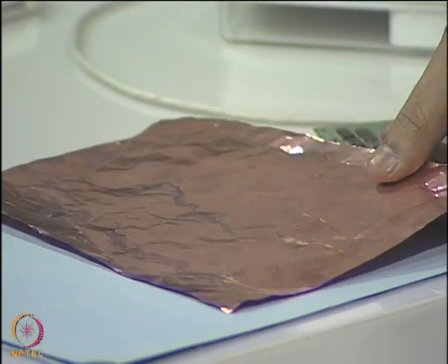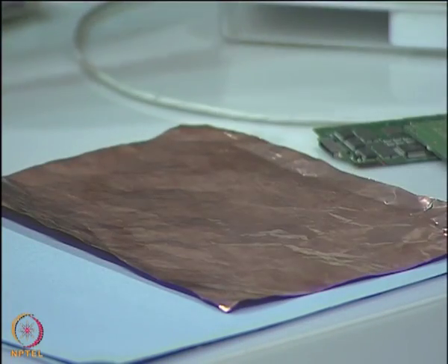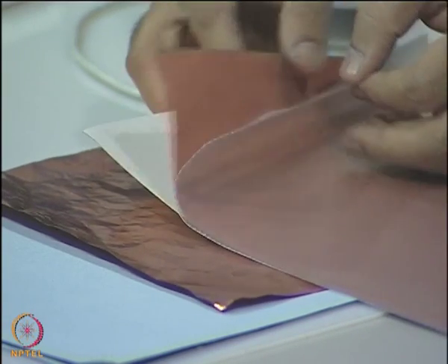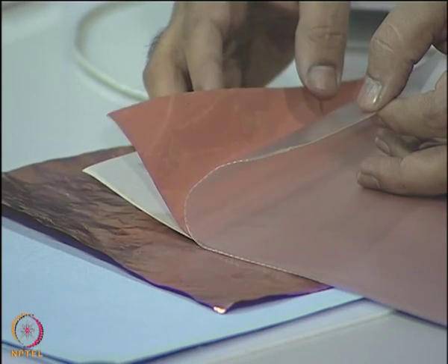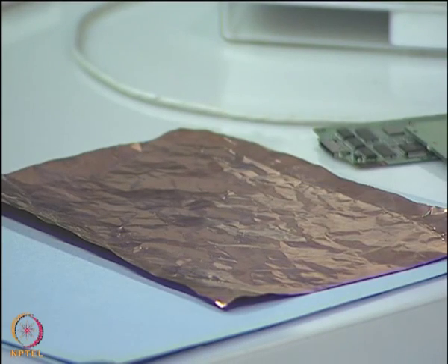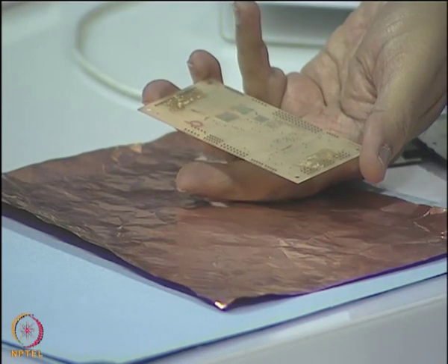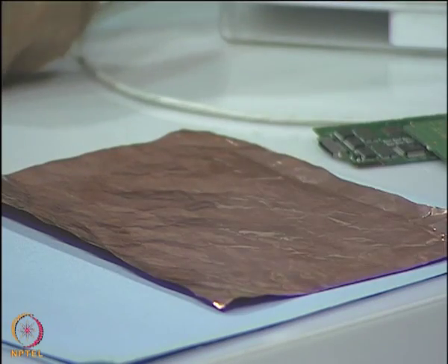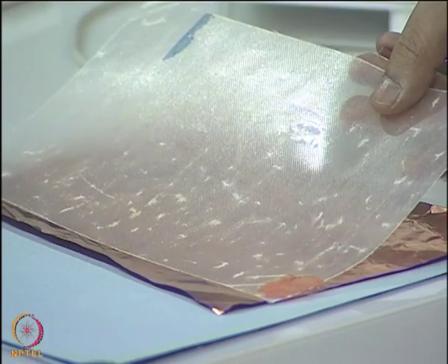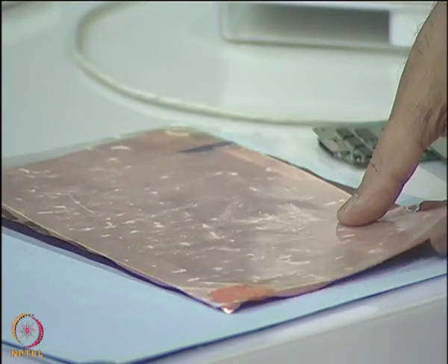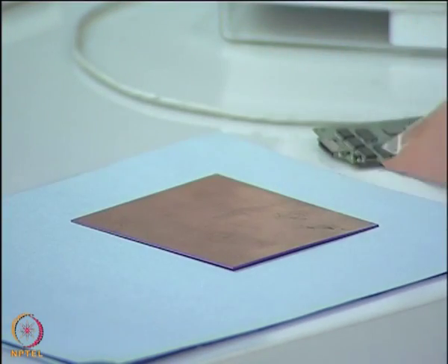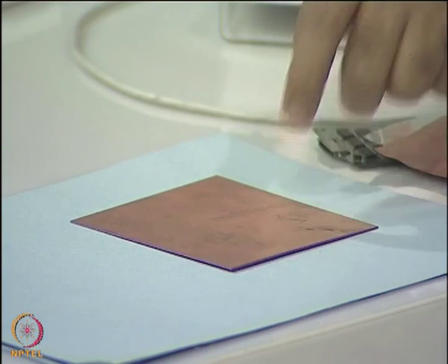See here, this is a copper foil. Now, the copper foil can also come in very thin sheets. You can see here, this is a copper foil, you need to handle it very carefully. These kinds of materials are basically laminated to these board structures to get a Copperclad laminate. This is an example of a dielectric material. What I am showing here is a dielectric material. So, you can imagine a copper foil and a dielectric material sandwiched to produce a Copperclad laminate like this.